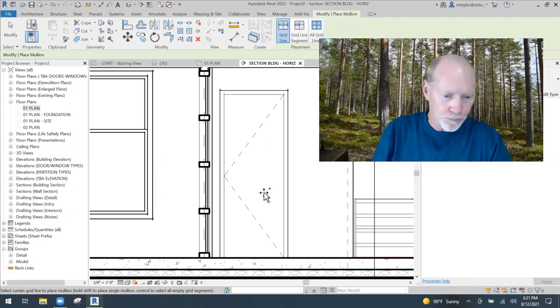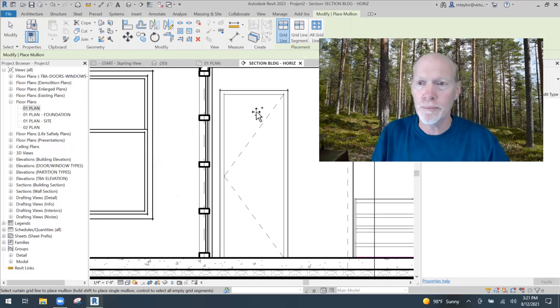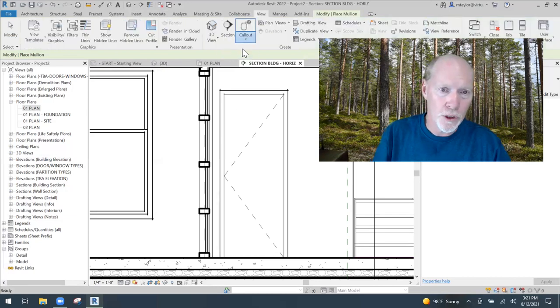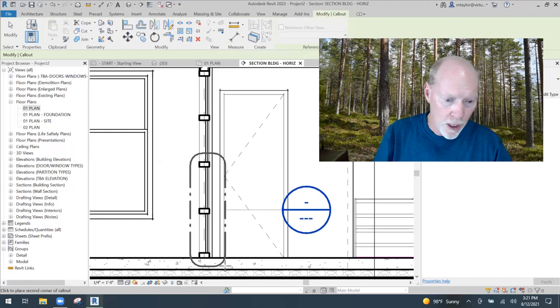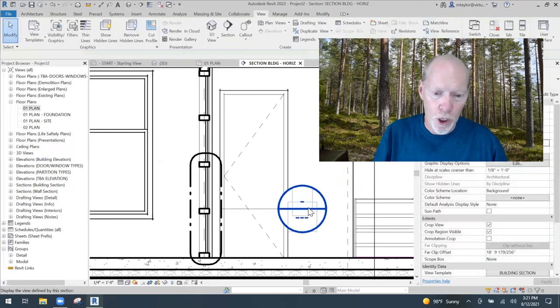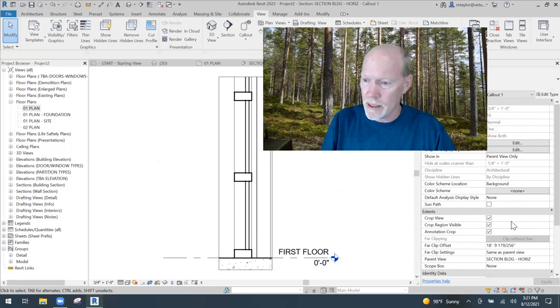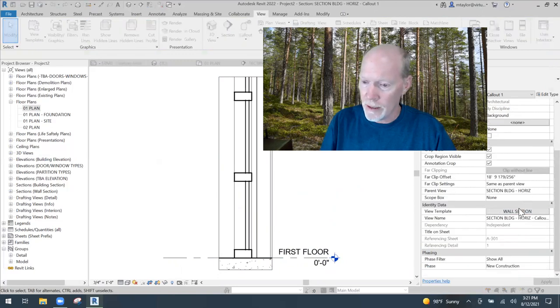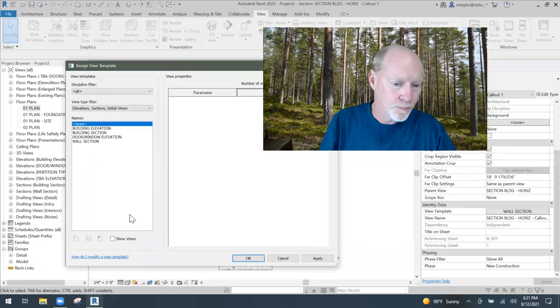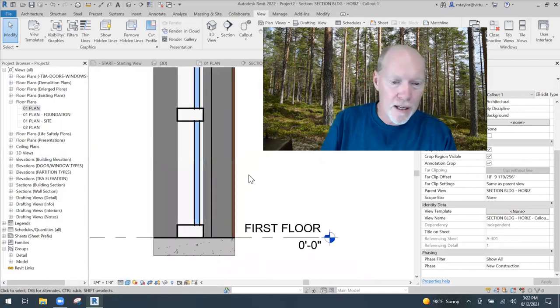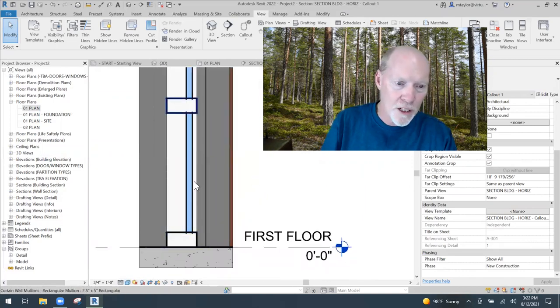So here we go. All right, what I'm going to do, I'm going to go to view, and I'm going to make a callout of this. View, I'm going to make a callout, just a rectangular callout, right there. Whoops, there we go. And I'm going to go to that callout. And so here it is. I'm going to make this not have a view template, set it to none, so that I can pop this up to consistent colors. There we go. Can you guys see that? What we've got is the glass is blue and the walls beyond are gray. So it helps us to see what we're doing here.